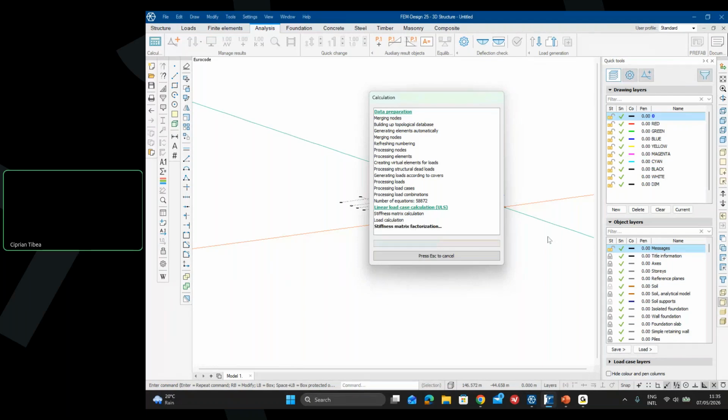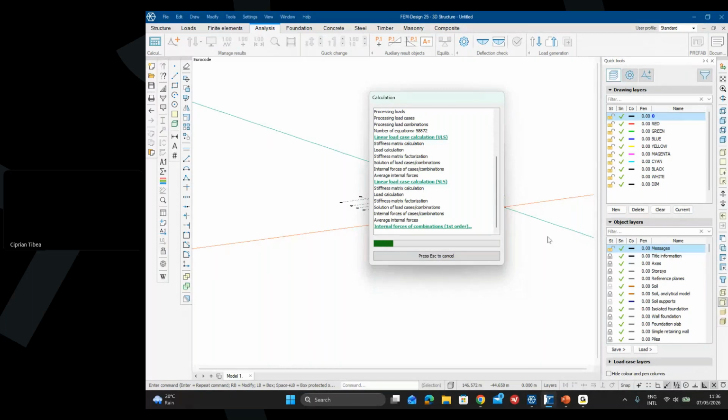Yeah, so going back to what I was about to tell you, and told you partially actually, there is a way to determine the optimal mesh size, beyond which the gain in terms of accuracy is too small, but the computational time is far longer if you go past that point.